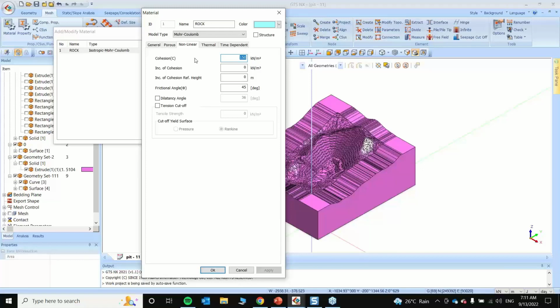Something you have to remember is that for Mohr-Coulomb, there are 5 inputs: the E, nu, gamma, C, and phi. This particular FEM slope stability method is only applicable to Mohr-Coulomb, modified Mohr-Coulomb, hardening soil, and generalized Hoek-Brown. For rocks, we use Mohr-Coulomb and generalized Hoek-Brown for the input properties. Both will support the SRM method in here.